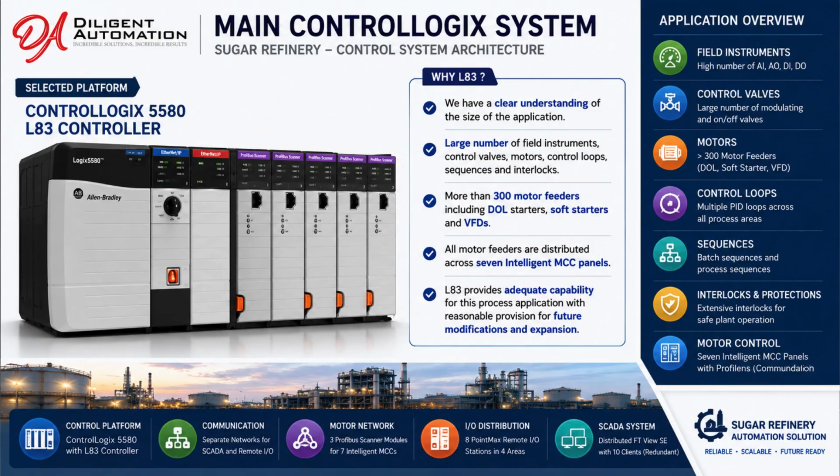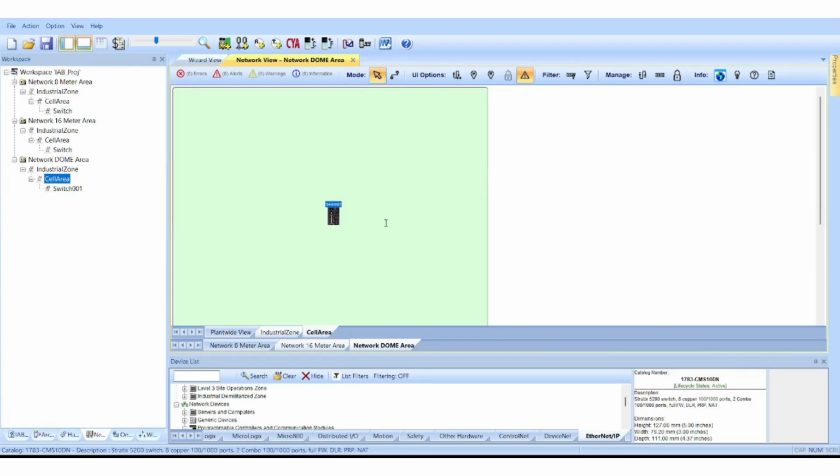Now let us start with the controller platform. For this project, we have selected the ControlLogix 5580 platform with the 1756-L83E controller. The L8 series gives us significantly improved processing capability compared with the previous L7 series generation. It also provides an embedded gigabit Ethernet interface and sufficient user memory for our application.